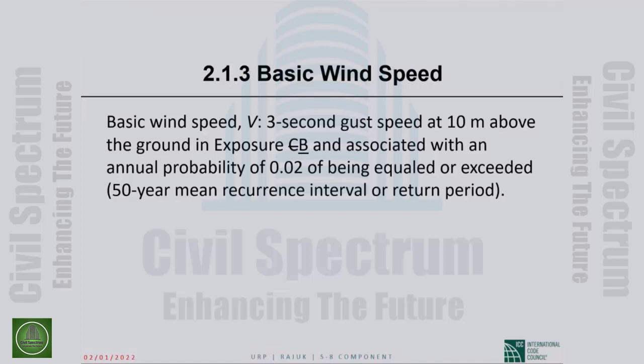This process goes on for a year or longer. And then they take the highest 3-second average as the 3-second gust speed. Okay. Bangladesh, the process that was gone through, I don't quite know, but it will be something similar. The Meteorological Survey of Bangladesh must have done something very similar. Okay. So 3-second gust speed.